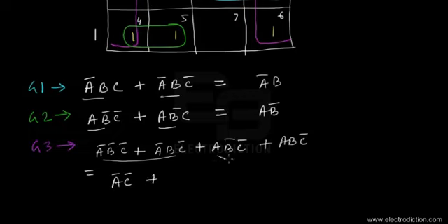And then again we do the same for the second two minterms also. And from over here we find that we have the variables A, C bar as common. So we're just extracting A, C bar, and the rest is just reduced to 1 again by Boolean algebra laws. And finally over here we have C bar common, so we're just extracting C bar out, and whatever remains, that's A bar plus A, is just equal to 1 again by the same laws of Boolean algebra. So finally we got A bar B, AB bar, and C bar as the reduced results.